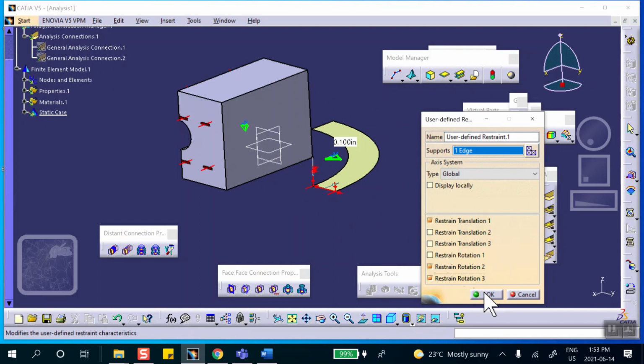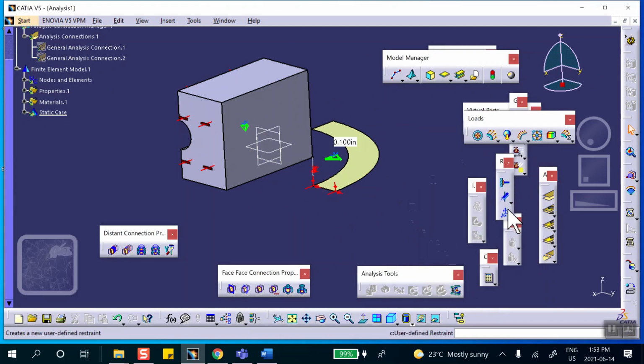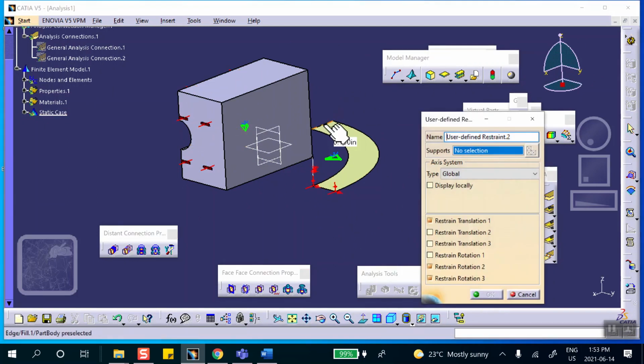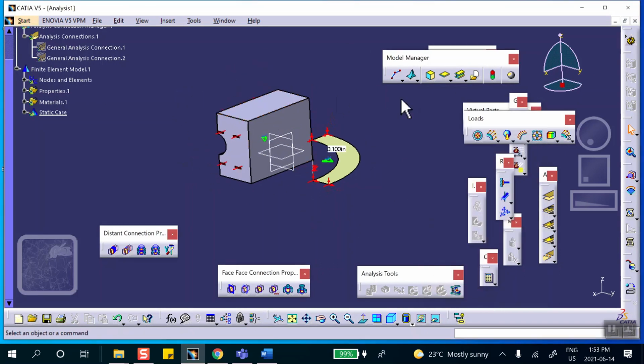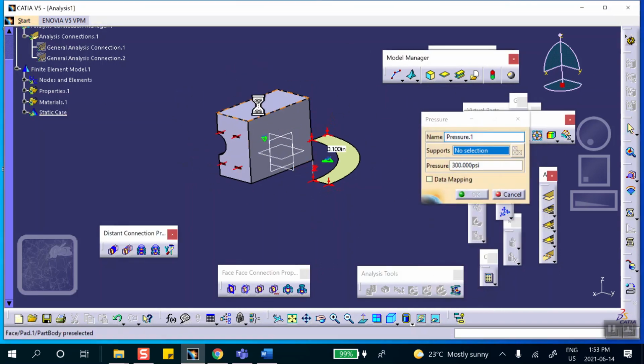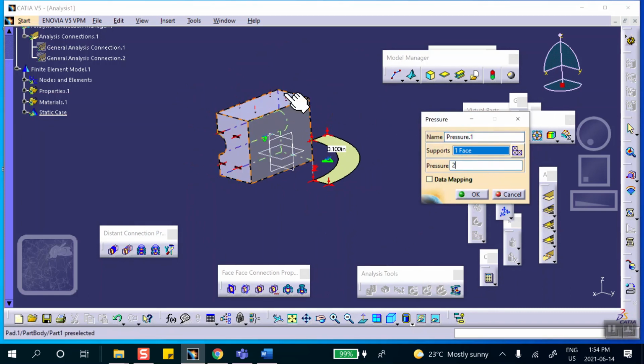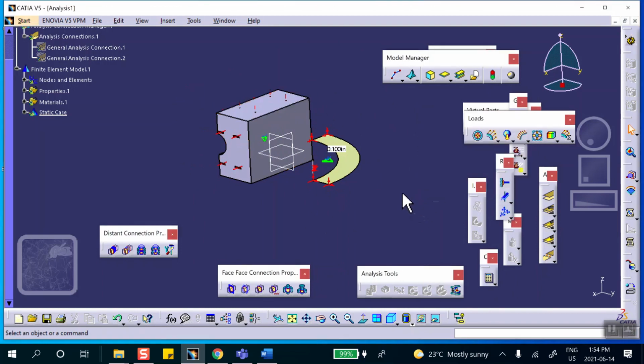The other edge on this side is in the exit plane. Exit plane means that it does not move in Y. Rotation is opposite. Okay, and finally you put the pressure up here. The pressure was, you were told that it's 2 psi. On that top face, the fact that you're taking 1/4, the pressure is still the same. Okay, so I think that's it.